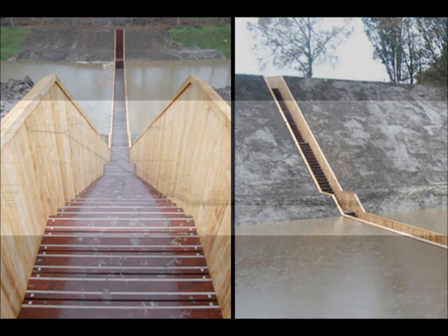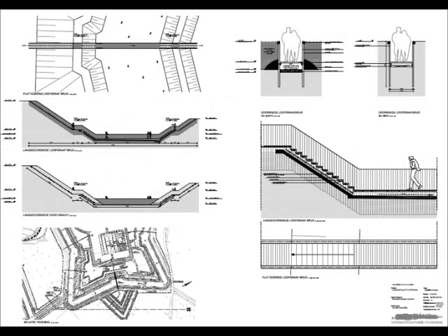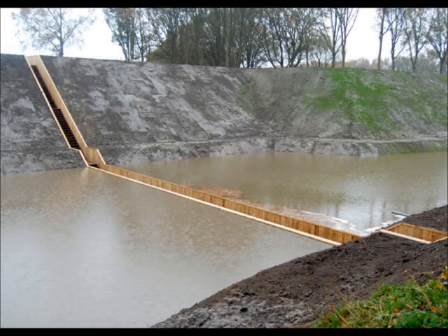The first place is at ground level, but it drops to cross deeper water. To achieve this, the structure is anchored to the ground by steel piles. The entire structure is covered with Accoya wood and materials specially treated to waterproof the bridge and resist erosion by the water, protecting it from fungus and increasing its durability.